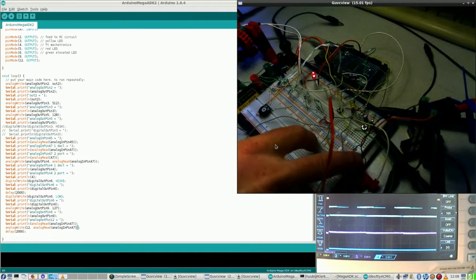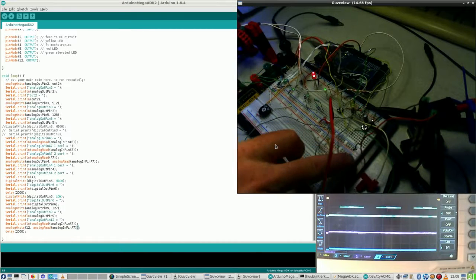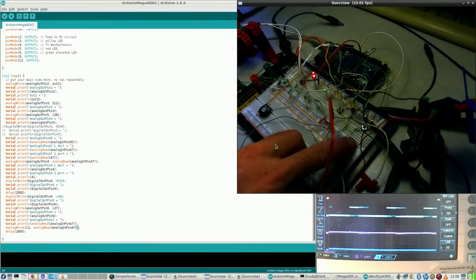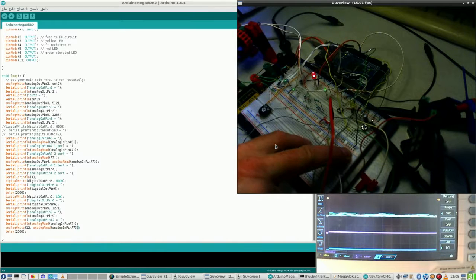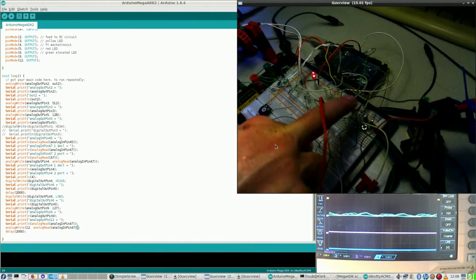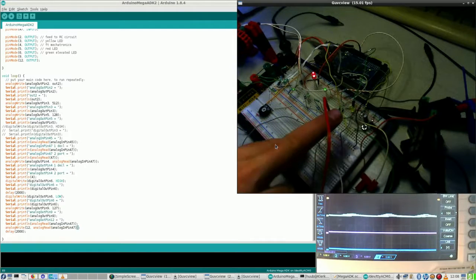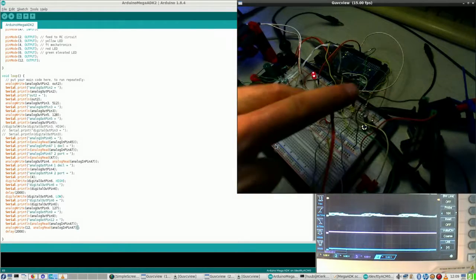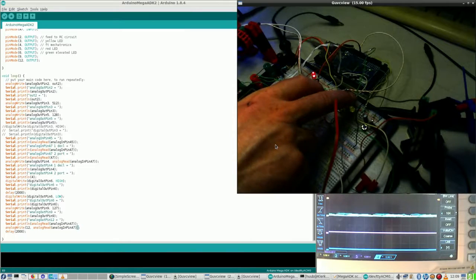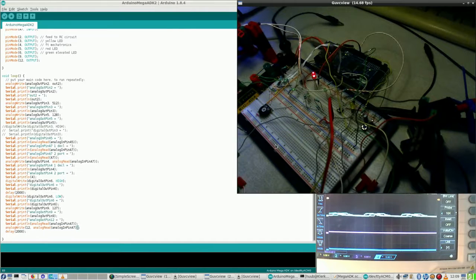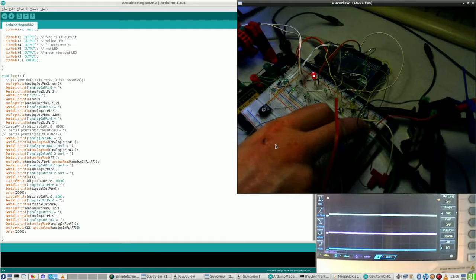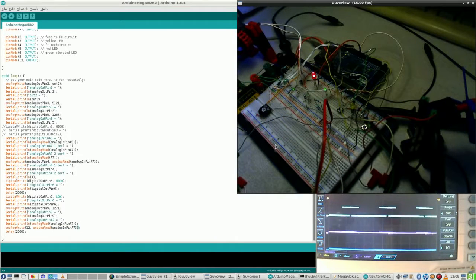And in trying before, I connected this wire, the black one, according to my other projects, to power, but that had an undesired effect because the LED started burning brightly because it got its power through the motor and not its signal, or its signal was completely overwhelmed and overtaken, so that doesn't help. And right now it's just nothing.